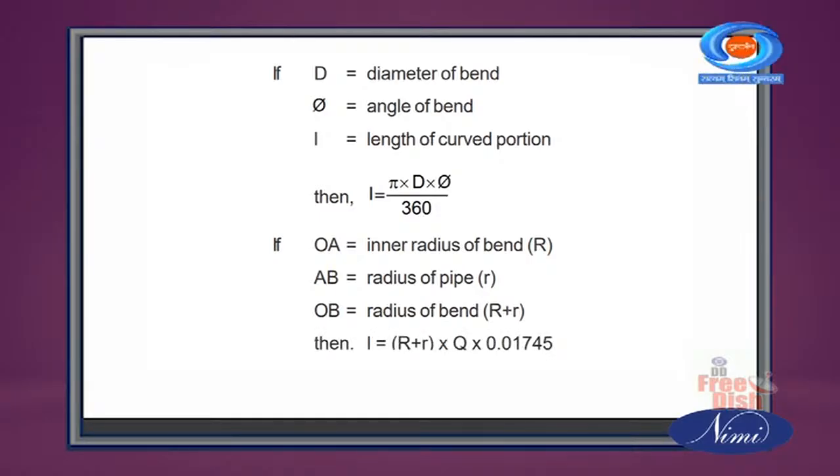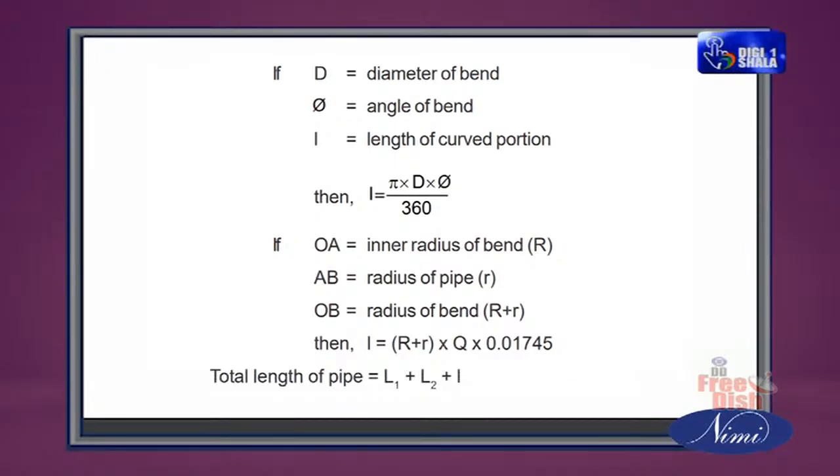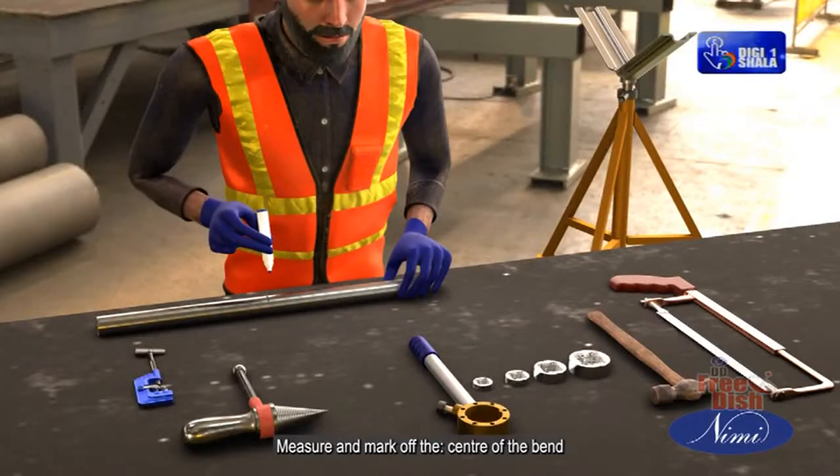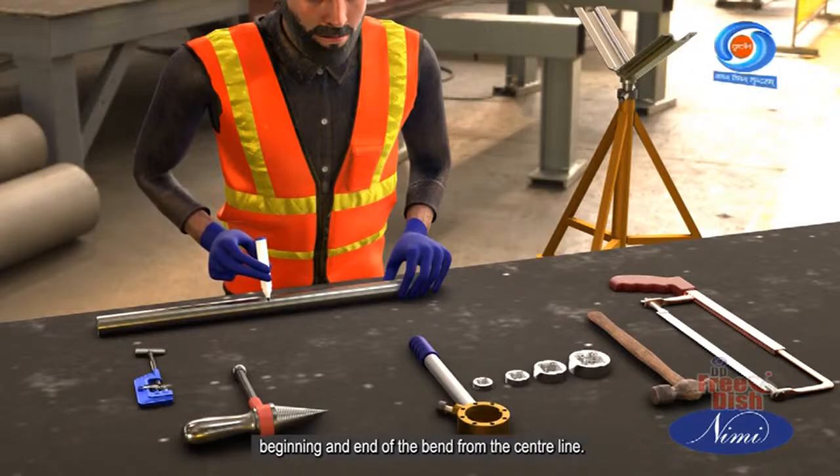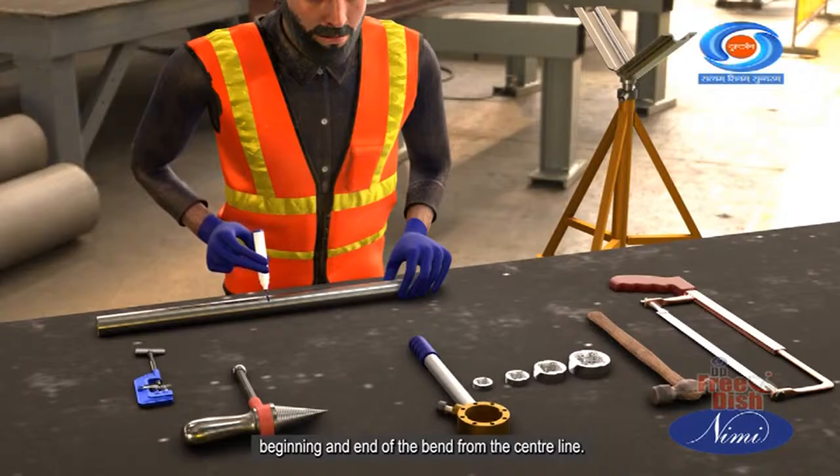Then L is equal to R plus r into theta into 0.01745. Total length of pipe is equal to L1 plus L2 plus L. Measure and mark off the center of the bend, beginning and end of the bend from the center line.